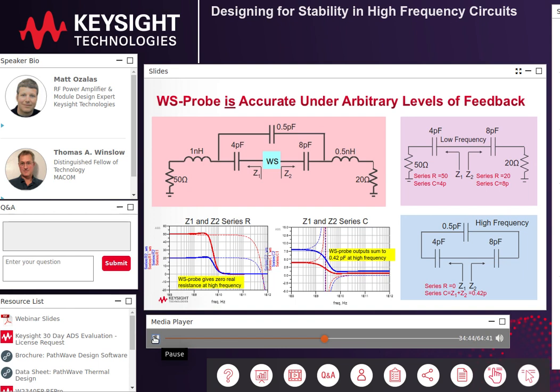Take the bidirectional impedances provided by the probes, convert those impedances into the series RC equivalent models, and study the example. You will see that the new probe provides sensible and accurate results that can be understood by inspection of the circuit. The old S probe clearly provides nonsensical results when the feedback becomes detectable and substantial. And it's exactly when feedback becomes aggressive in our circuits that we want these impedance probes to be their most robust and their most accurate for both impedance analysis and stability analysis.